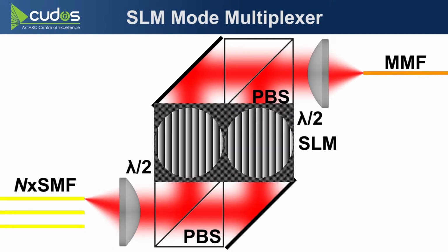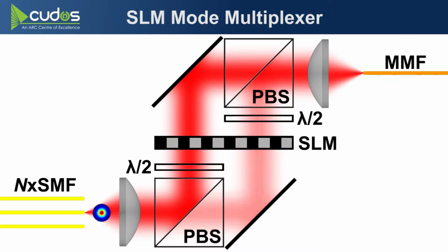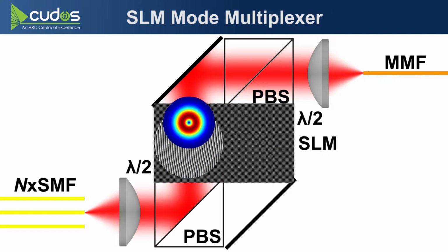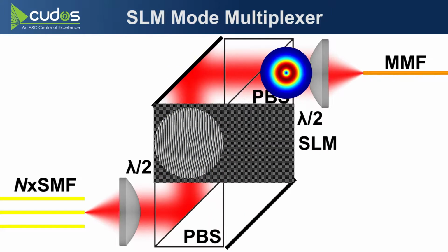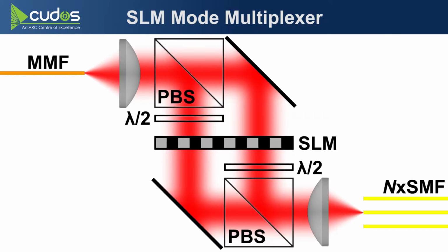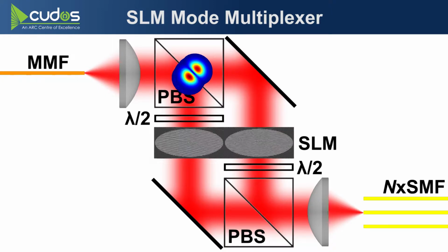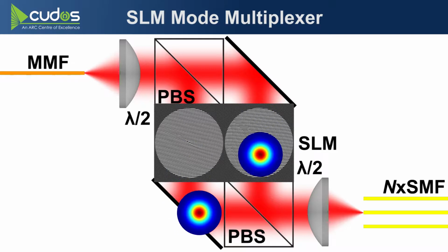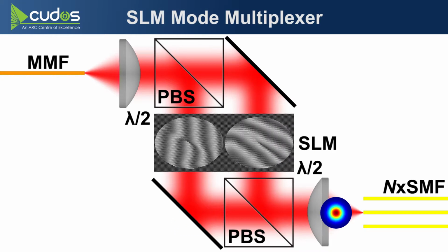So in practice it plays out like so. A Gaussian beam comes in in some particular polarization, the phase mask converts it to a higher order mode which is coupled into the fiber. Along the length of the fiber, that mode undergoes mixing as per the mode transfer matrix, and it arrives at an identical system at the receiver which plays out the process in reverse. The mode comes out, masks convert both polarizations back to Gaussians and couple them into the output single mode fiber.